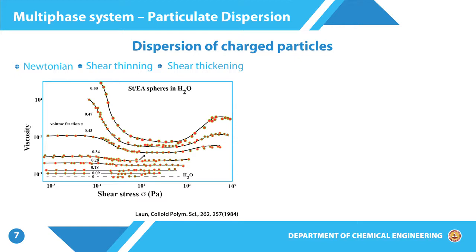We will see that quite often when we are dealing with materials, especially with paste like materials or materials which seem to have a yield stress, it becomes useful to plot the data in terms of stress as opposed to the shear rate, because till a certain stress there is no flow, and therefore, we can read off the yield stress value from such data.